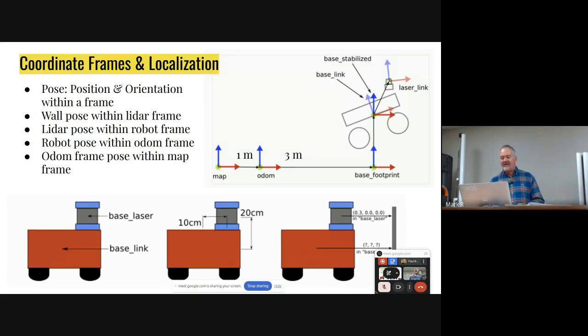So what happens if we asked our robot to drive 3 meters, but it only drove 2.9 meters? The software monitoring the LiDAR output and comparing it to the map observes that the robot only drove 2.9 meters, but odometry says it drove 3 meters.